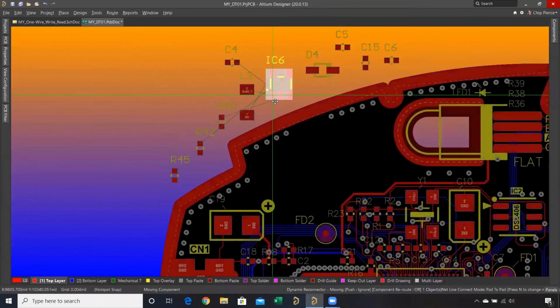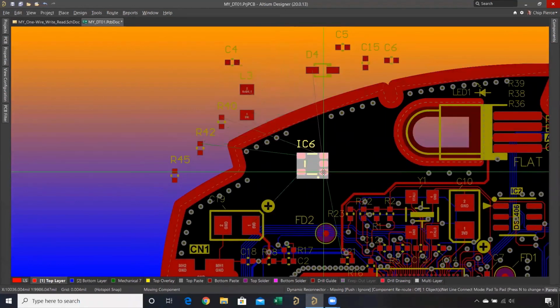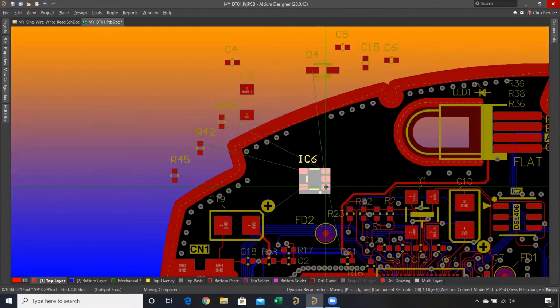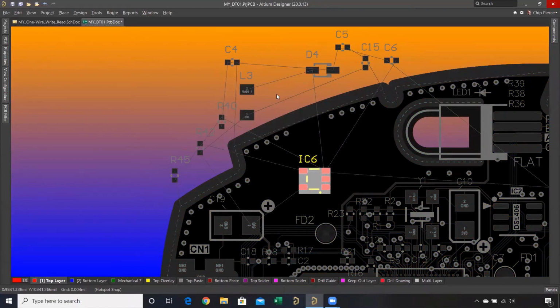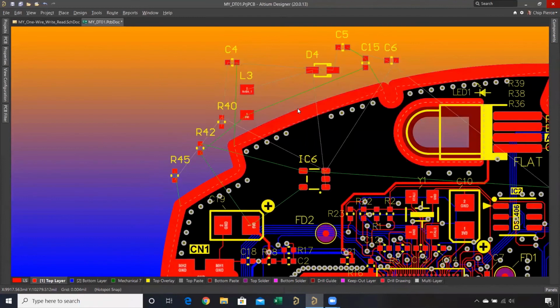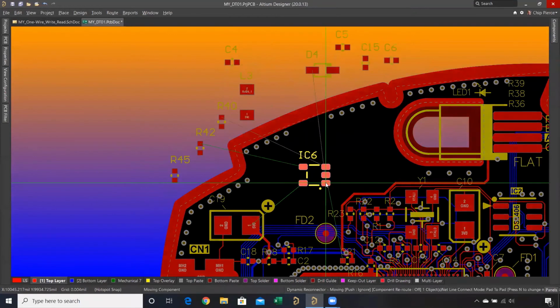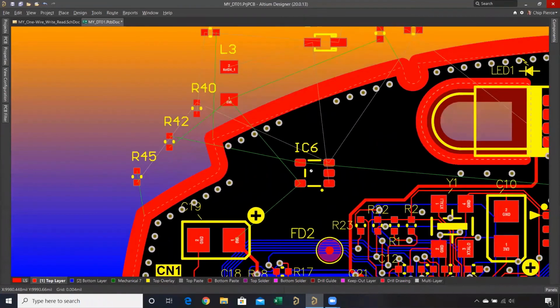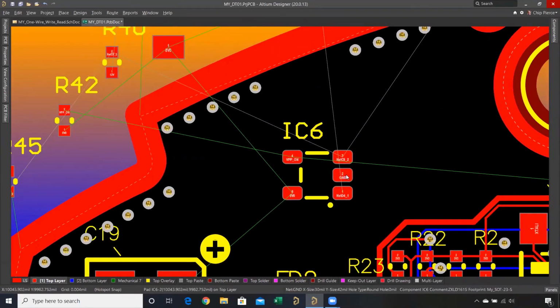You see when I move this footprint right here, and now I hit the space bar to rotate it, and I'm just going to preliminary place it down there. Because guys, what I recommend, you place your larger footprints first, right? Okay, so right click and clear filter. And then I'm going to use these connection lines as a guide. Now be careful though, there's a zoom threshold for seeing the net names and the pad numbers on these pads as I get in a little bit closer.